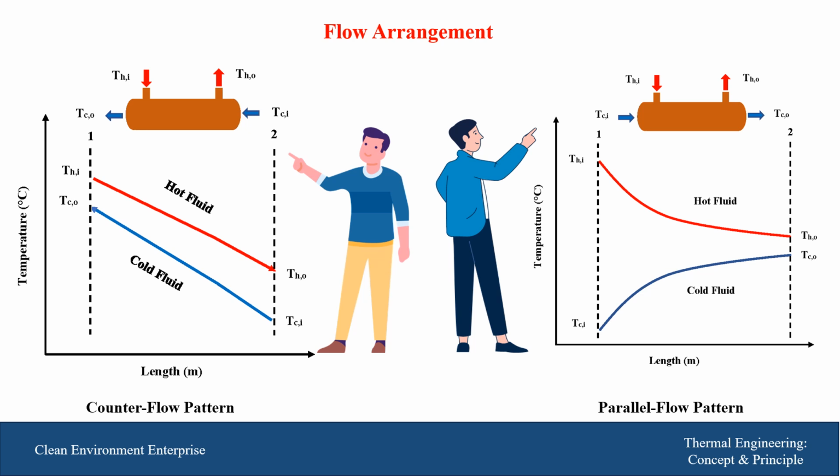In general, all heat exchangers are preferred to have counterflow. In the counterflow, there is a uniform temperature distribution and they provide a good temperature difference between both fluids. So it is more efficient than the parallel flow pattern.